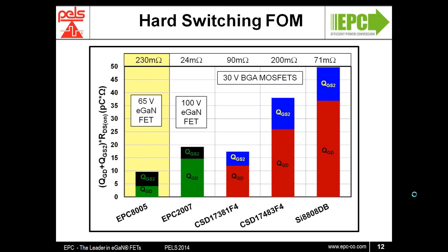Furthermore, having a good figure of merit isn't enough to make a good switching device at high frequency. Because of the high frequency and high switching, high dV/dTs are unavoidable. A device with a high dV/dt turn-on immunity is required. To achieve this, the QGS1 term must be much larger than the QGD of the device. The QGD is the plateau charge, as shown previously in the idealized hard switching diagram, while QGS1 is the charge subthreshold of the device.